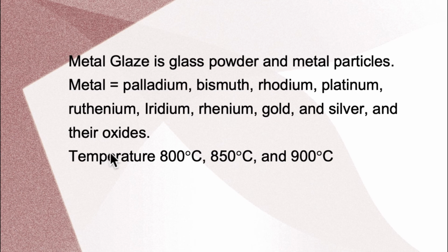After the application of the metal glaze over the substrate, the material goes to a kiln. Nitrogen instead of regular air is the solution to avoid oxidation, and the temperature reaches between 800 degrees Celsius and 900 degrees Celsius. In the end, the parts are cut to the right size. A laser cuts the metal glaze to reach the correct resistance.